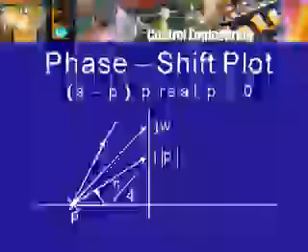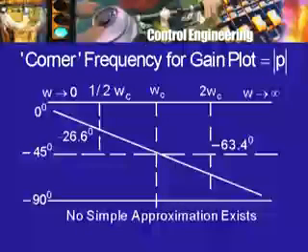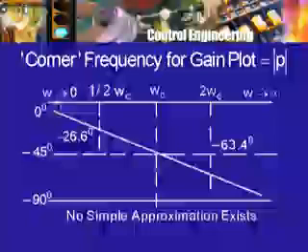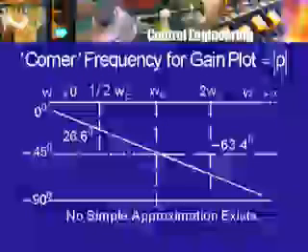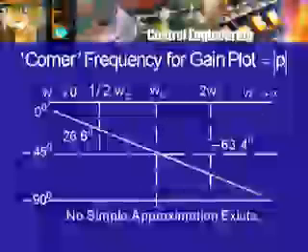So, from this we know that if I were to plot, and now I am not showing the scale of the omega axis as logarithmic because there is no log occurring anywhere. So, I am just drawing a horizontal line to show the omega scale. The phase shift is going to vary from nearly 0 degrees or a small negative value towards the low frequency end, so omega tending to 0, to minus pi by 2 for omega tending to infinity, that is the high frequency end.